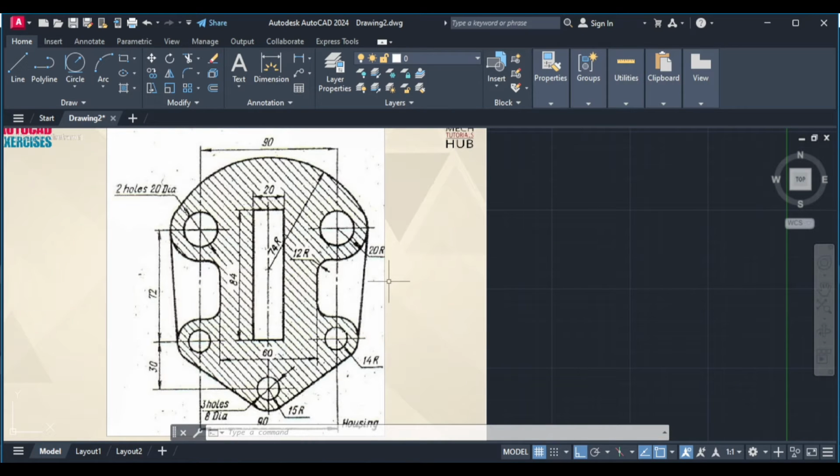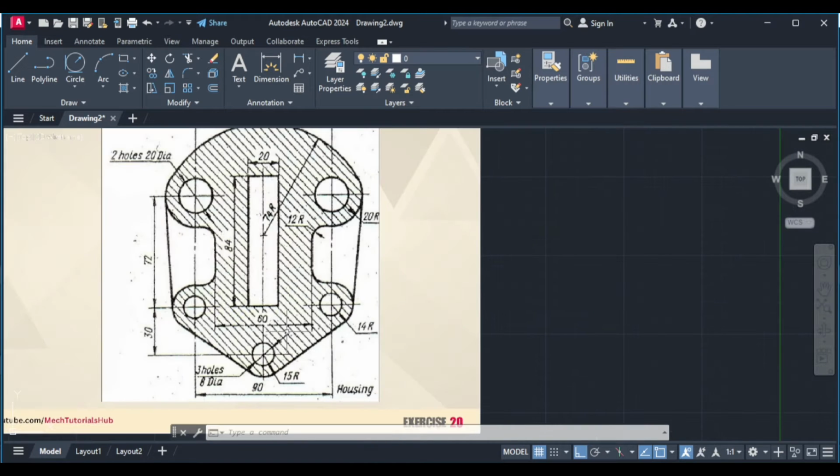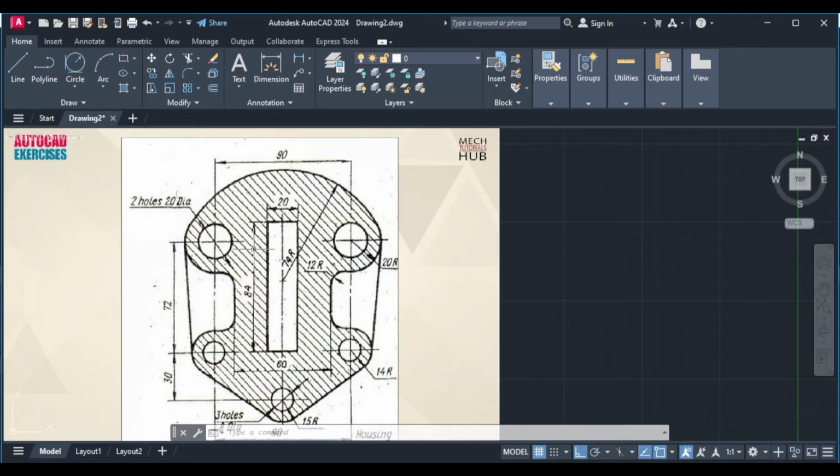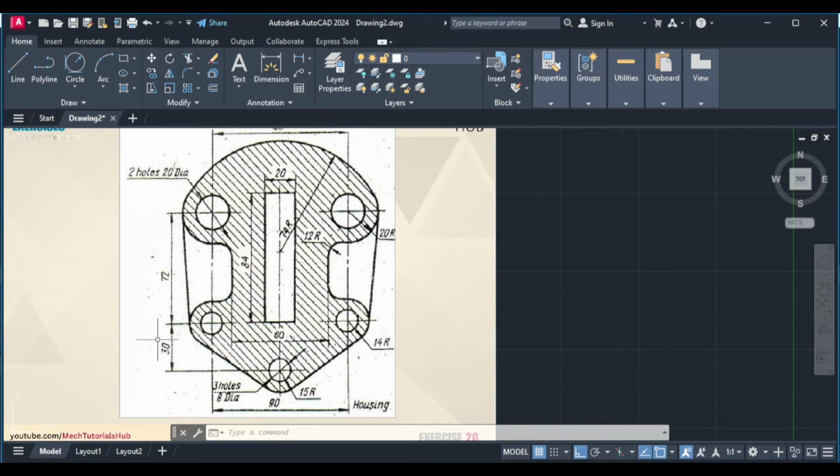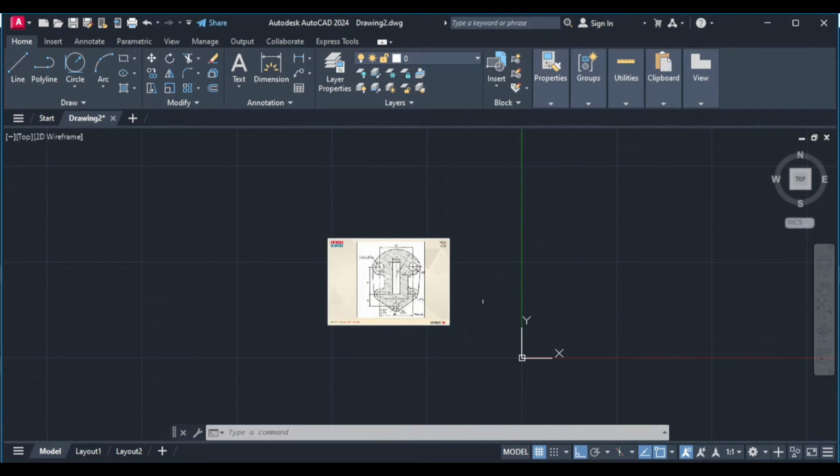In this session I'll be discussing how to generate the sketch using AutoCAD. So have a look at the sketch. I'll start from the central vertical line, then slowly I'll explore the sketch stepwise. There is an offset on either side at a distance of 90 where I have circles. The overall height of the sketch is 70 plus 30, 102, followed by an outer radius of 74. So I'll take around 160.